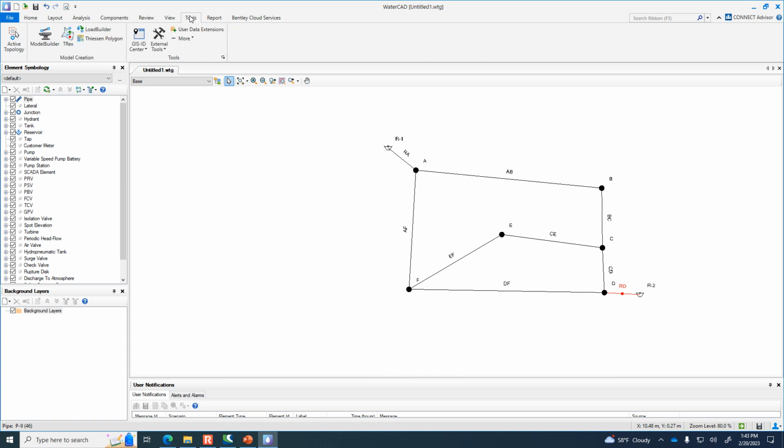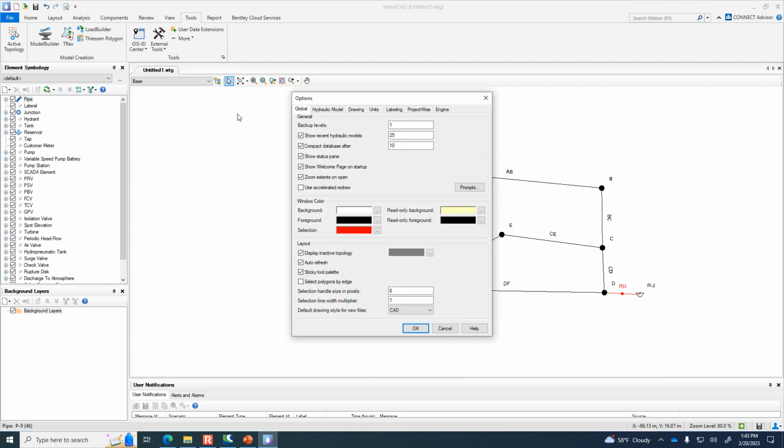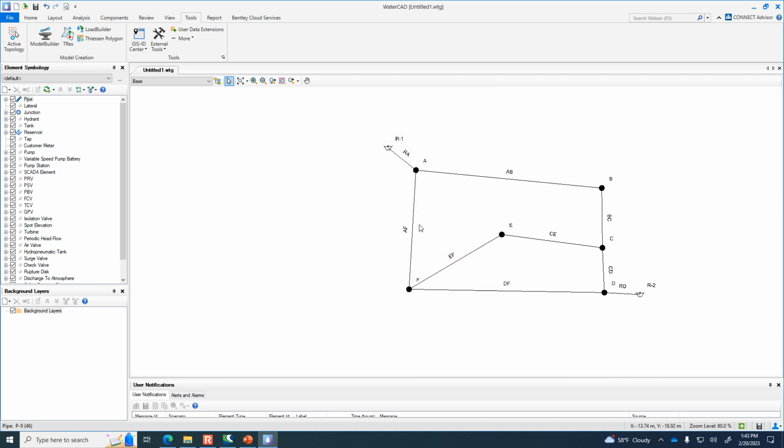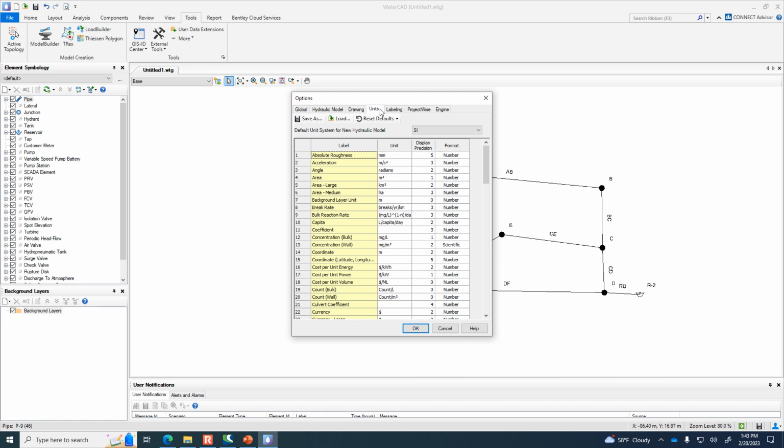Okay, so go to Tools, and then More, Options, Units, and yours should maybe say Traditional, U.S. Customary, so switch it to SI. And once you switch to SI, maybe you don't have to start over. We might be able to get away with it. It's early enough. So again, to get there, it's under Tools, Options, Units, and then... Flex table is still in standard units.